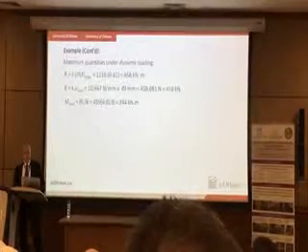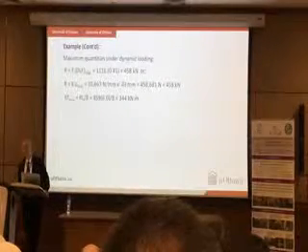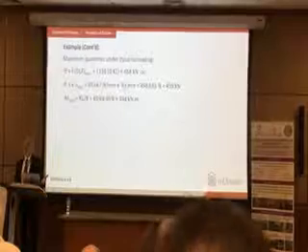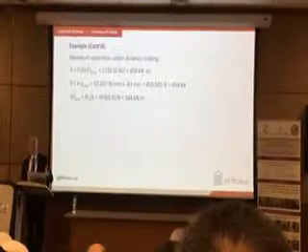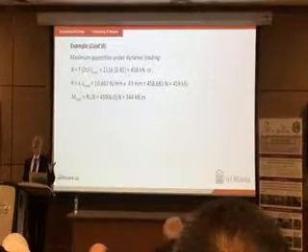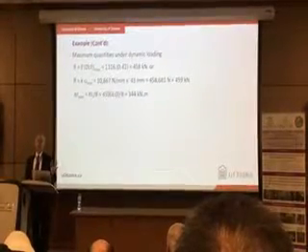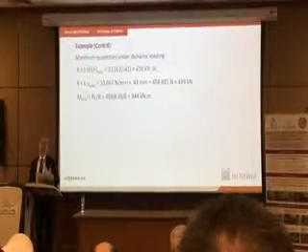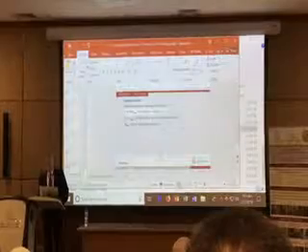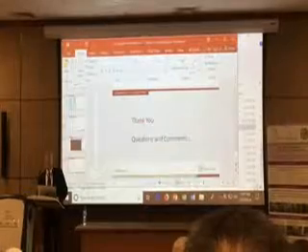So from that, I can find the dynamic moment, which comes out to be 344 kilonewton-meters, for which I provide reinforcement and design this column if I want it to remain elastic. Okay? So here the key is remaining elastic, because when we go to building standards and codes, things may not remain elastic depending on the level of protection and performance levels that I choose as a designer. Okay? So now we're going to discuss performance-based design for blast, and that brings us to our second presentation.